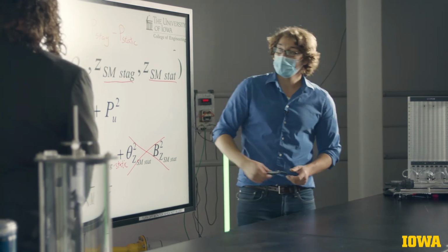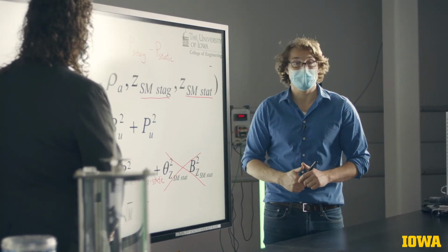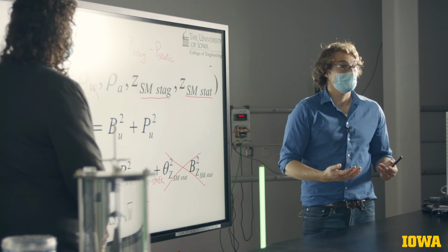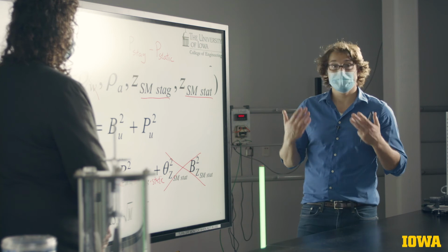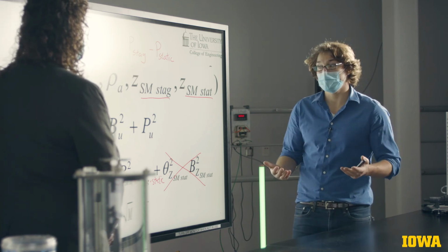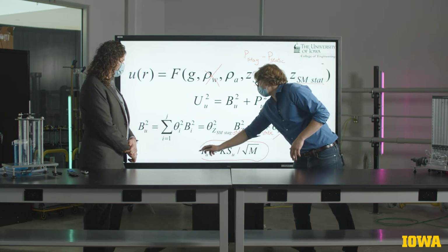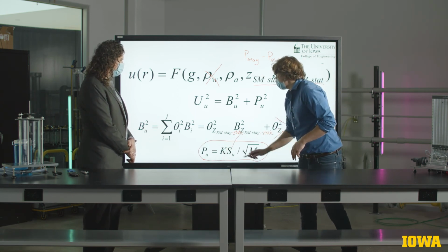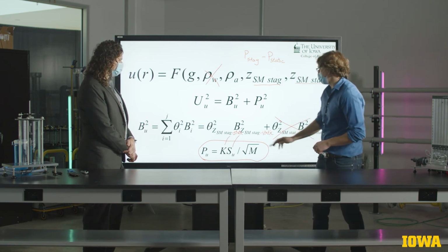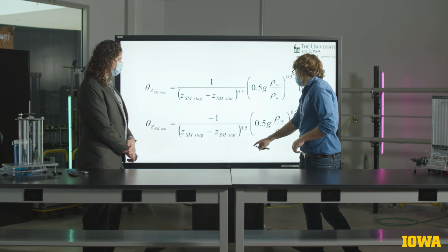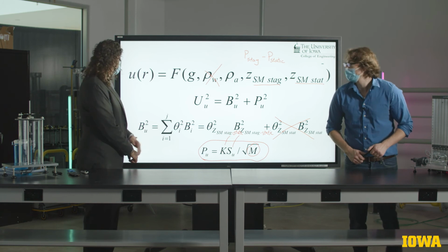You may recall that when I was using the Pitot probe to scan the velocity distribution across the pipe, I repeated the measurement near the wall a number of times, 10 in total. So we have 10 measurements of the velocity, which we can use to calculate the sample standard deviation, multiplied by our coverage factor, which will be equal to 2 for a 95% confidence interval, and then divided by the square root of the number of samples, which in this case is equal to 10.